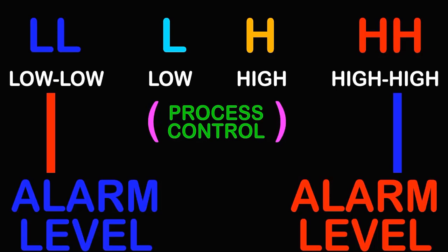Perhaps our heater broke. Perhaps a wire fell off. In which case, our logic is telling the heater to run. And as far as our logic knows, it can't tell that the PLC is broken. All it knows is it's energizing the output to the heater, and it should be running. When we look at our PLC, it's showing us a bit associated with the output that says, yes, the heater is on. The problem is, like any real-world appliance, sometimes they break, and when you turn it on, nothing happens.